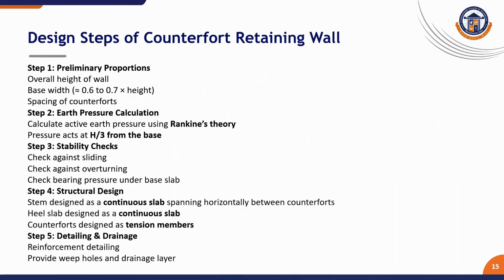These are all the design steps for the counterfort retaining wall: preliminary proportions, earth pressure calculations, stability check, structural design, and detailing and drainage.